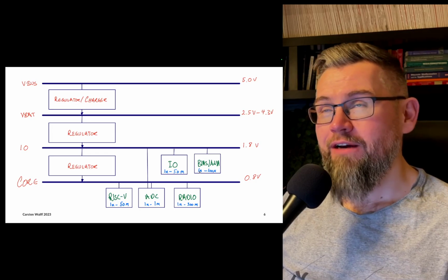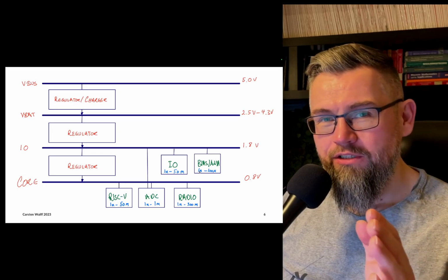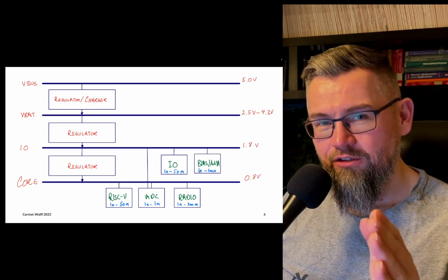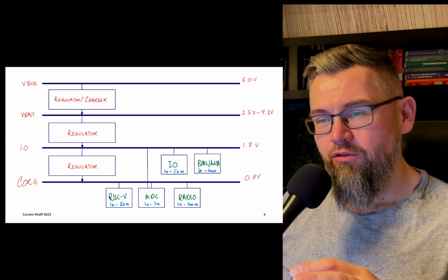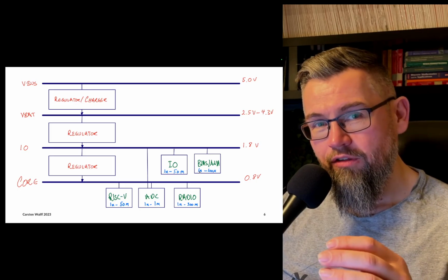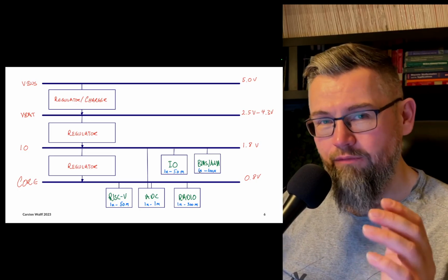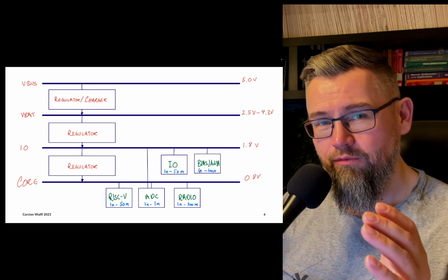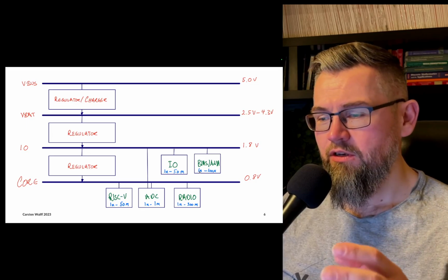You have to compute the time from a register where data starts to propagate all the way through the combinatorial logic to the register where the data is supposed to be captured, and you have to make sure that there is sufficient time between the clock edges for the computation to happen. That's setup and hold times.